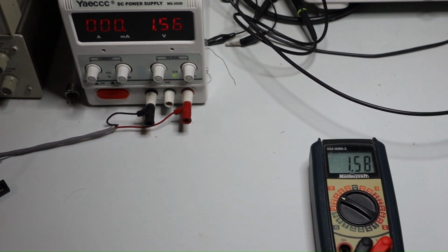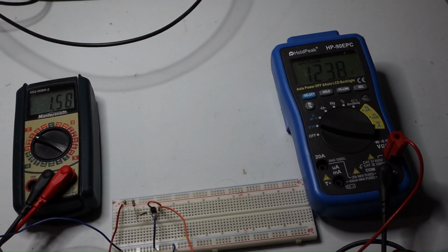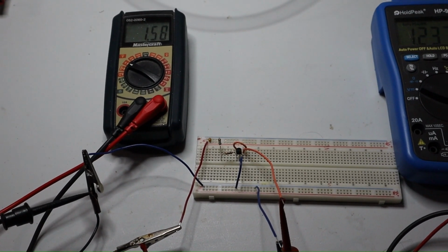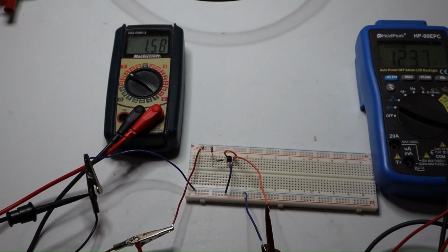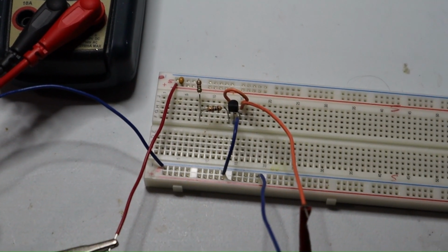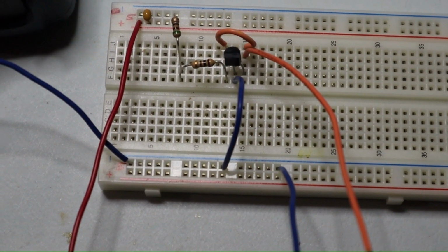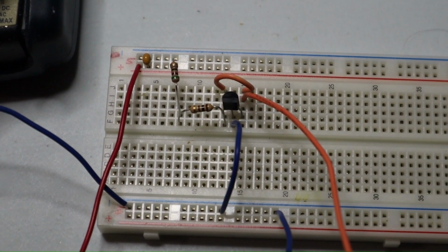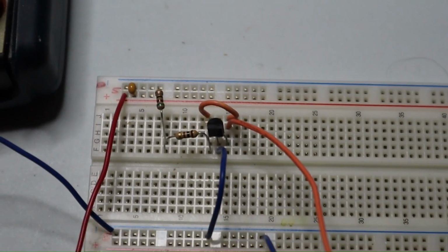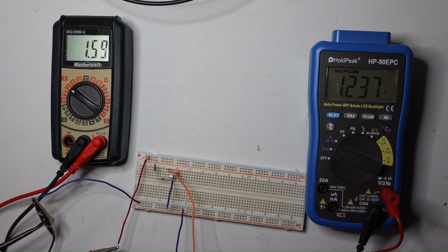I am trying to test the precision shunt regulator circuit. So this is the breadboard and the shunt regulator is shown here. This is the AZ431L. I use two resistors in series to limit the current below 100 milliampere, and two voltmeters were used. One is for measuring the input voltage and another one the output voltage.